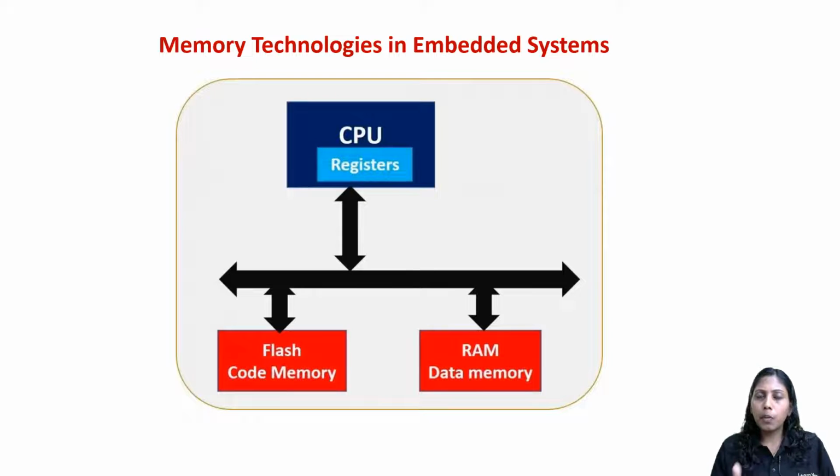We already discussed that microcontrollers are based on Harvard architecture. In a Harvard architecture, the program memory and data memory are separate, so that's the reason you see flash memory and data memory, both separated. Apart from that, something new you are learning here is the CPU registers. Keep this in mind: whatever data or instruction is in the CPU registers, the processor inside the microcontroller can access quickly.